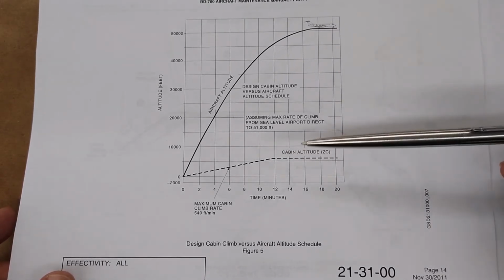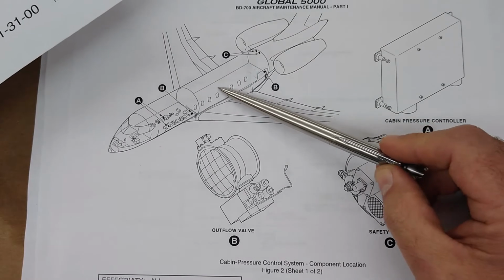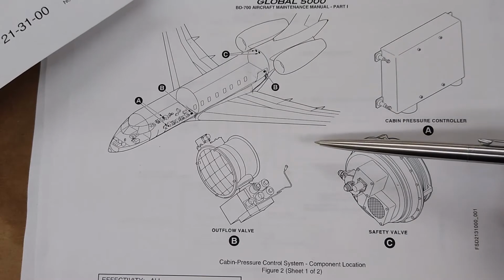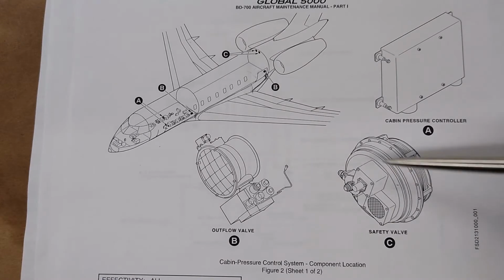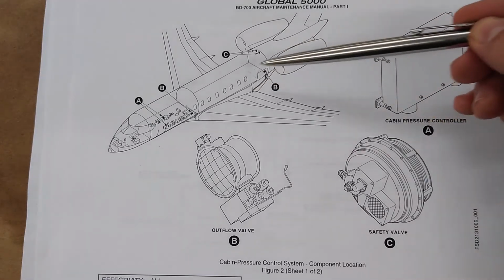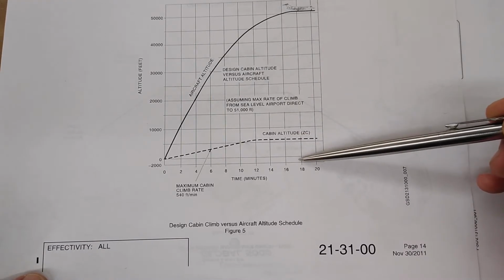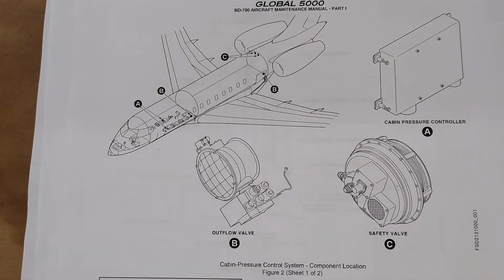The atmosphere is trying to get in, and it's supposed to get in through the packs, but if your packs quit working, now you have a negative pressure here. These safety valves will allow air to get into the cabin. So these have dual purposes: to prevent overpressurization of the cabin and to prevent negative pressure in case your packs quit working and you need to get air back in to pressurize the aircraft and to equalize it to the outside pressure when you're coming back down again. Now let's go take a look at those outflow valves in the aircraft.